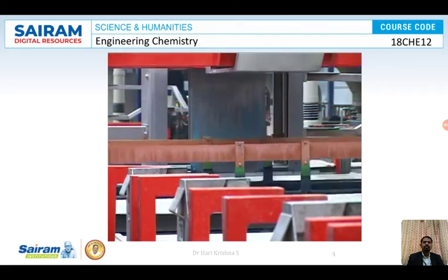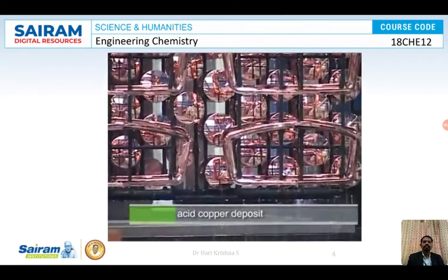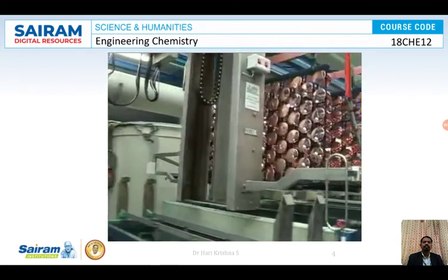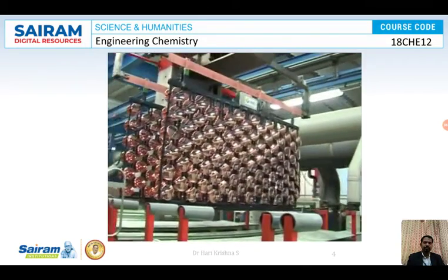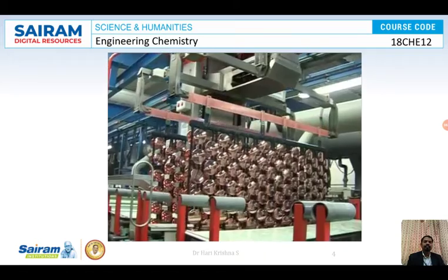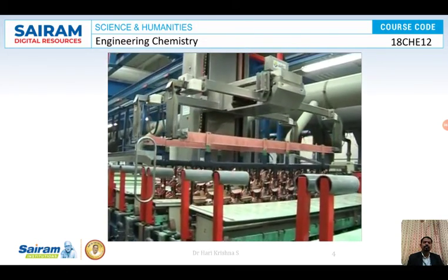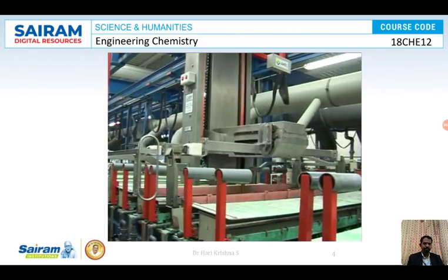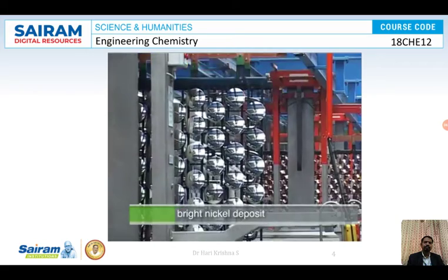Next, a 20 micron thickness layer of copper deposited from an acid copper electrolyte provides leveling of the etched plastic surface, while also producing a bright, smooth deposit. This layer also provides ductility between the plastic and other plated layers, which is important to improve the thermal shock resistance while also minimizing the formation of cracks when the plated part is in service. A bright nickel deposit from 5 to 7 microns provides protection of the copper layer, gives a final bright aspect, and supports the chromium layer.